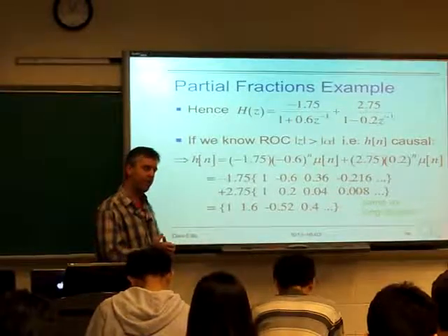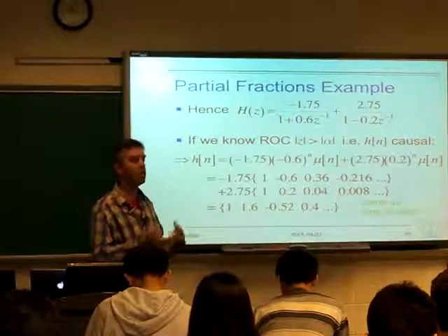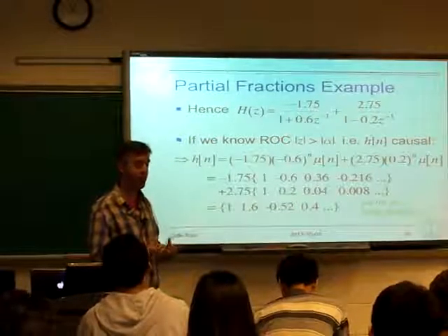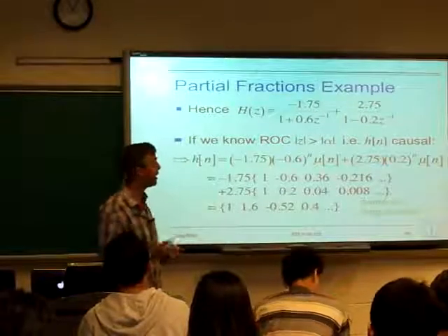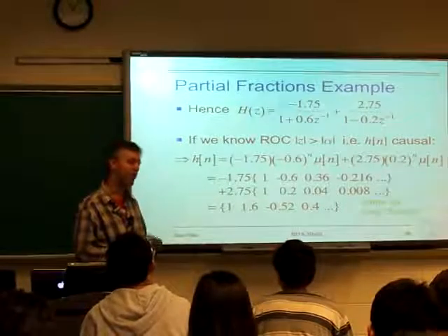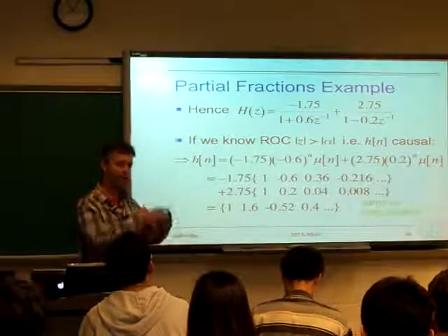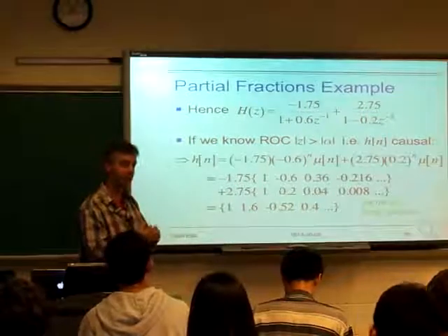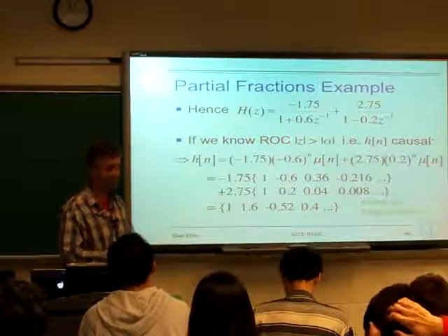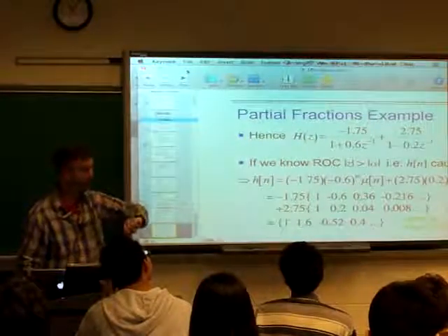In the Fourier transform, there are situations where you're thinking about some signal, some system, you end up with a Fourier transform, and you want to know what it is in the time domain, you actually need to do an inverse Fourier transform, most often an IDFT, because that's the one you can calculate in MATLAB. In the Z transform, I've never had a situation where I've actually wanted to do one of these for real, full up. It's always been that I only care about this because I can get its Fourier transform, and then I just do the inverse of the Fourier transform. But I'm sure other people have.